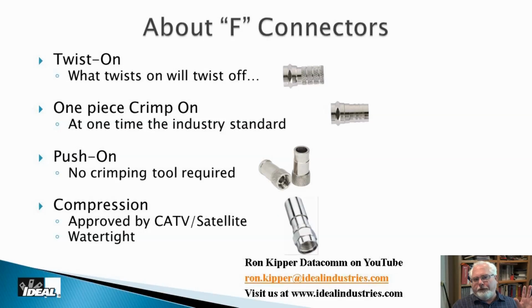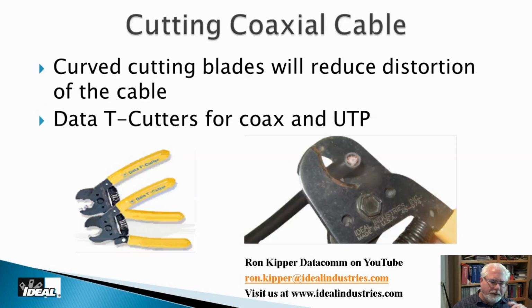But the only connector up here that's any good is the compression connector you see here. And we sell an industry-compliant connector. Installed properly, it'll pass all the tests the SCTE says it has to pass in order to be approved by the cable and satellite companies. But you'll find that most satellite and cable companies have all gone out and spec'd one or two brands, and that's all they install. But we do actually sell a pretty good little connector right there.